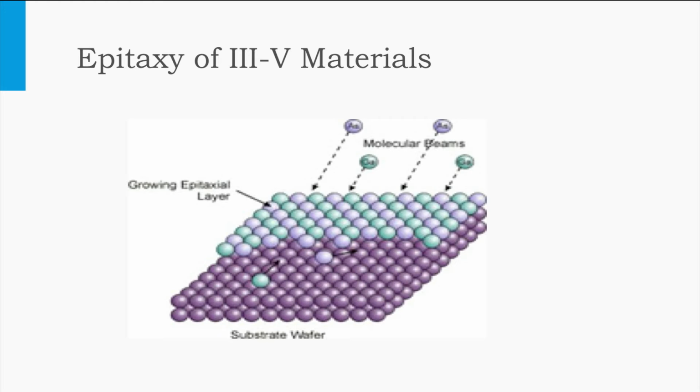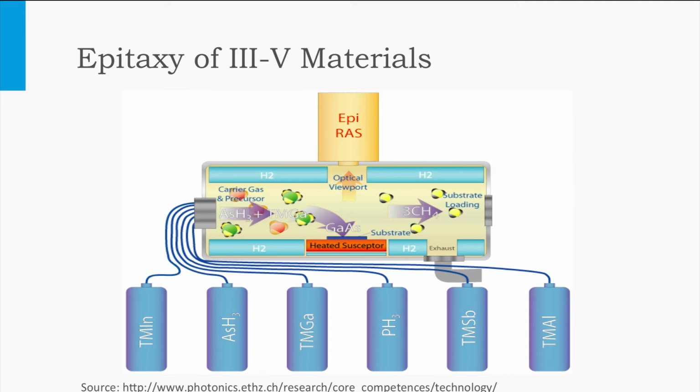The gallium arsenide crystalline lattice is grown layer by layer and adopts the structure of the crystalline substrate. The relatively slow layer by layer growth allows the deposition of compact materials without any vacancy defects. Furthermore, processing at high vacuum conditions prevents the incorporation of impurities. Dopants can be added to make it N-type or P-type. 3-5 semiconductors can be deposited up to a very high degree of purity.